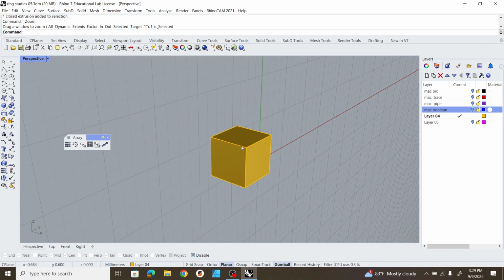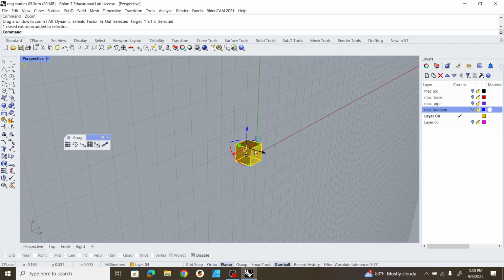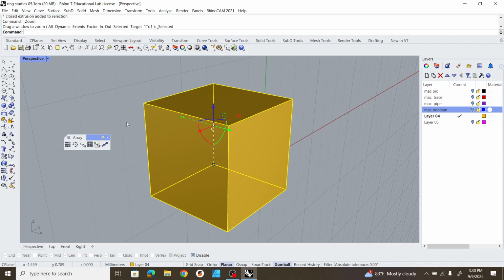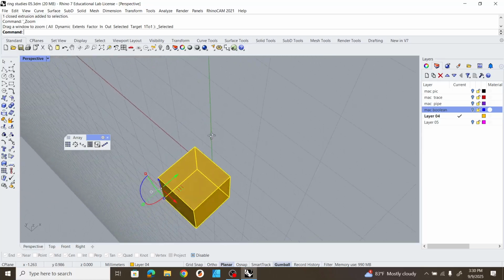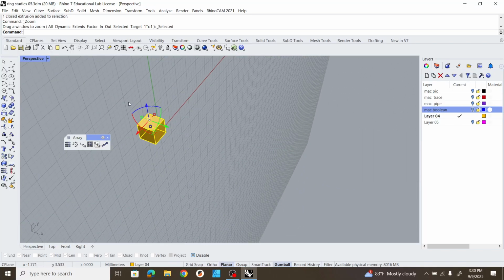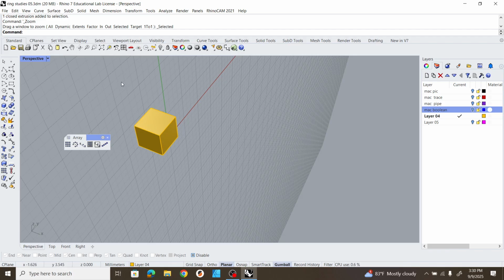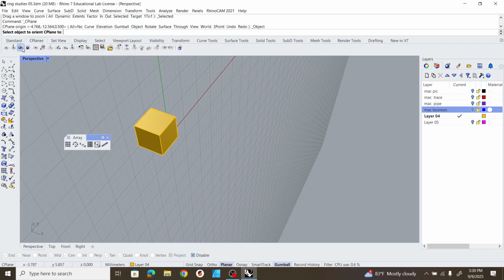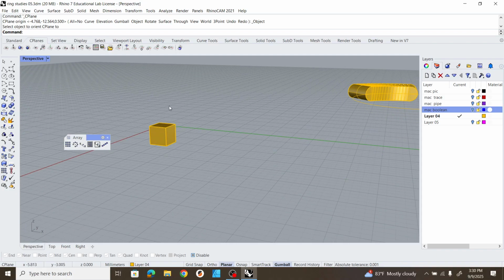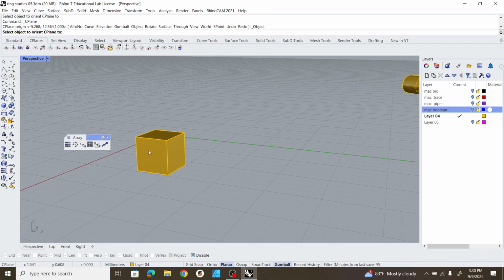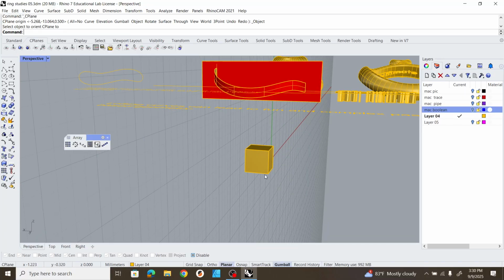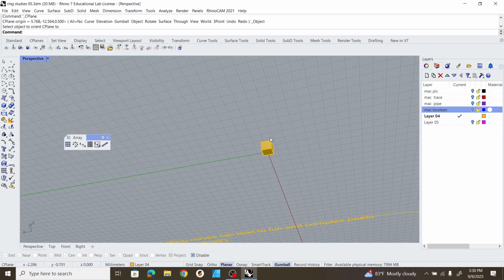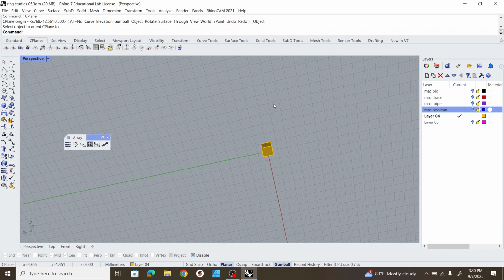Basically, you just pick whatever object you want to zoom into and hit that button, and it allows you to rotate around that object. That's like your center of vision if you're having trouble navigating the space. But yeah, you can just go back into that and set it to any part of your surface. And that just allows you to then draw curves and stuff on that.